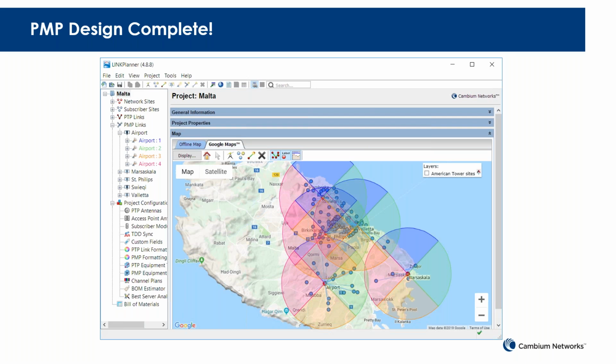The other way, obviously, if you know what channels are being used, then when you set up your channel plan, you need to try and ensure that the channels you set up are not overlapping with the channels being used by any existing sites that are already out there. If you know there's somebody out there with a 10 meg channel, and you're trying to put out a 10 meg channel, then you need 10 megs of separation between those two center frequencies. If it's two 20 meg channels, then you need 20 meg separation between those frequencies.